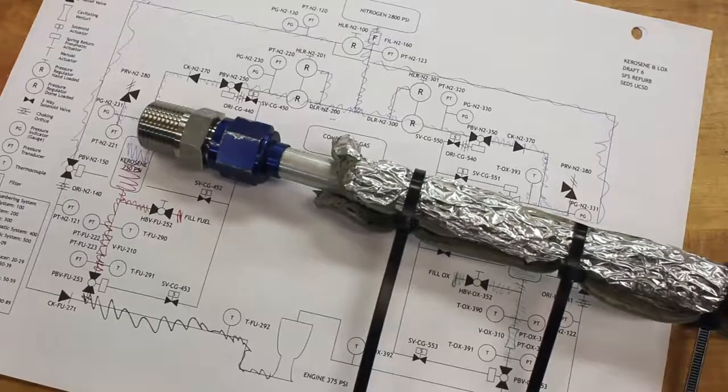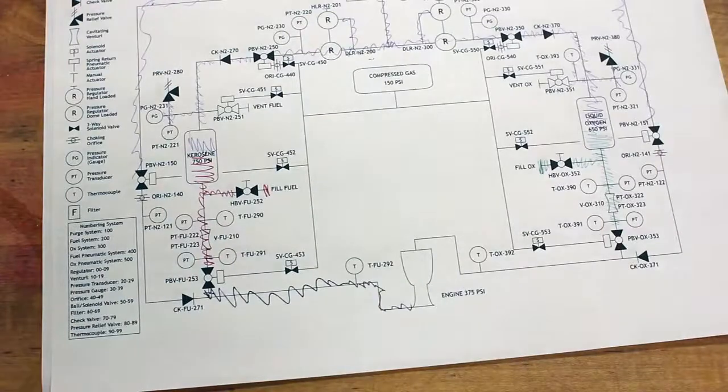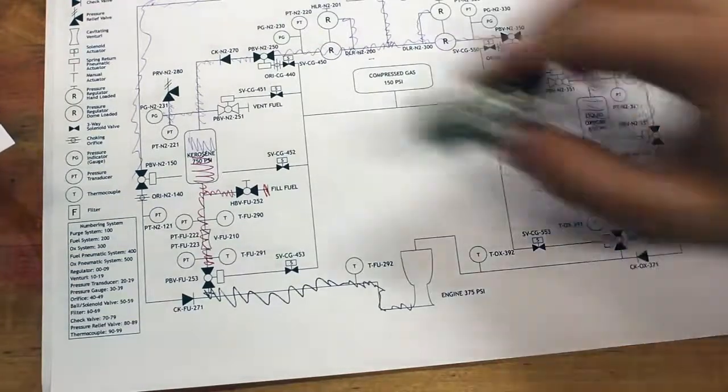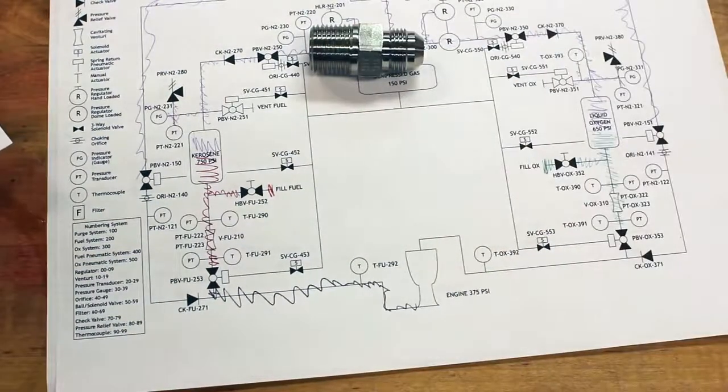We're probably going to buy our new ball valves with AN ends, so we don't have to worry about NPT, FOD, or anything like that. But it doesn't really matter. The tubing diameters we use are in accordance with mass flow rate. You just need to do a bunch of math to figure out your tube diameters, how to size your valves, and how to size your regulators. We'll be doing those calculations today. Any further questions about the PID, plumbing in general, flow control, anything like that?